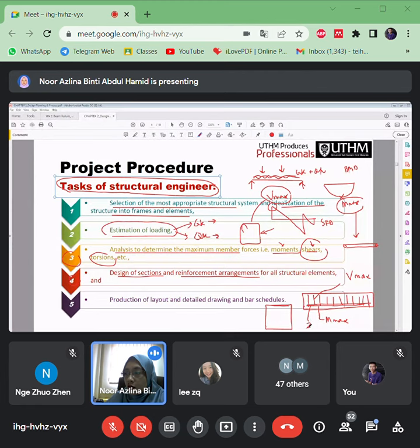provide with 2 numbers of high strength bar with a diameter of 20. So that means in the cut section of the beam, there will be two bars with diameter of 20. Okay, let's say for the links.